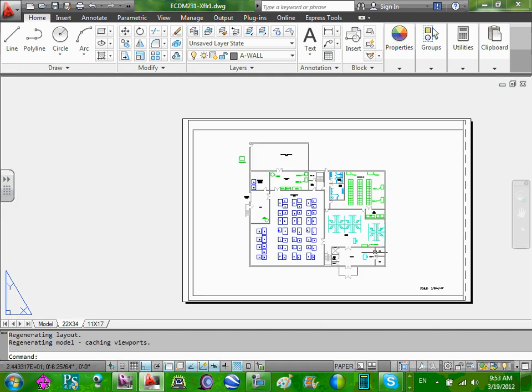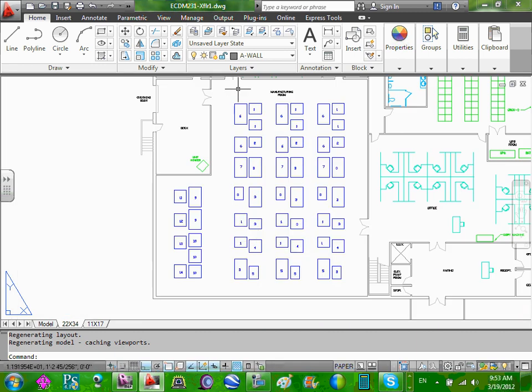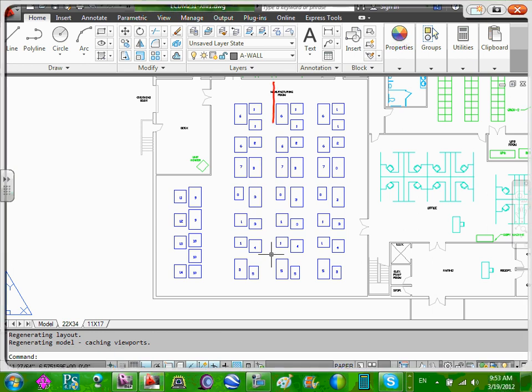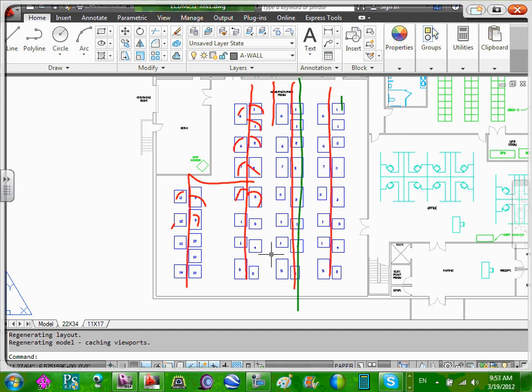All these machines, okay? So here's the manufacturing floor. When we bring the bus duct later on, guys, right at the top of it, right here, we're going to be feeding these machines depending upon the voltage. So bring, tap it, and come over here. And remember, there will be two bus ducts. Why two bus ducts? Because you have two voltages. So here's two bus ducts coming in and feeding whichever machine, 480. So we'll have two bus ducts running side by side and feeding these equipment. That's how we're going to do the bus ducts.